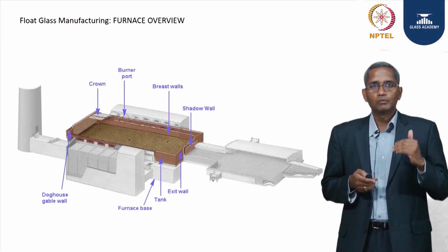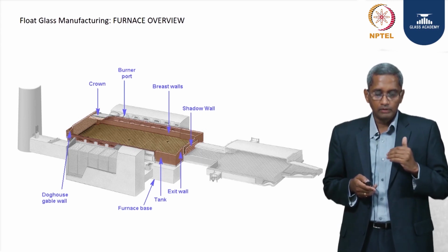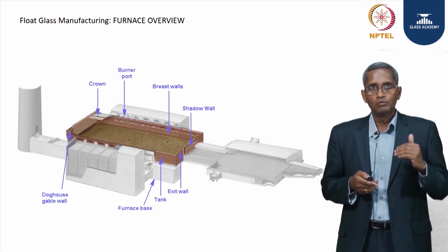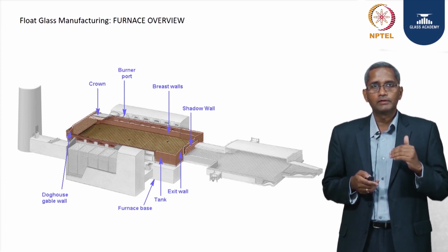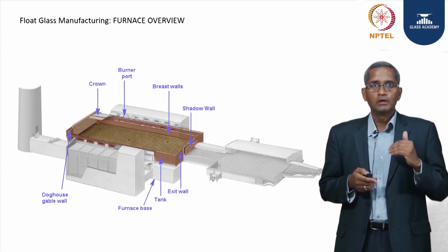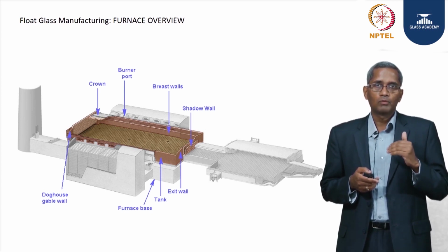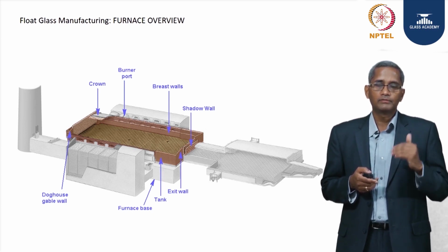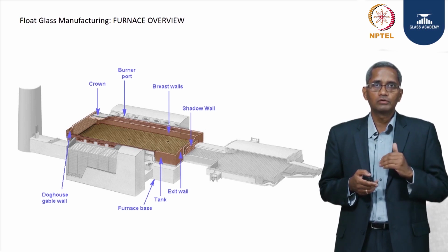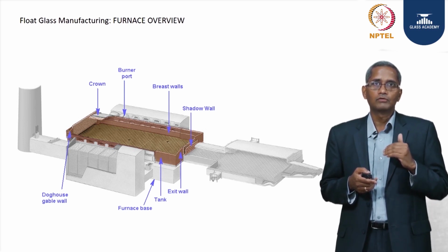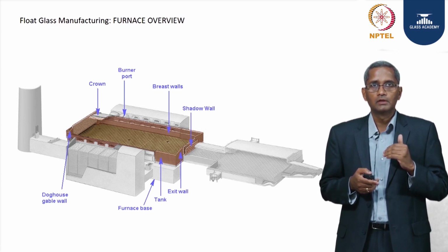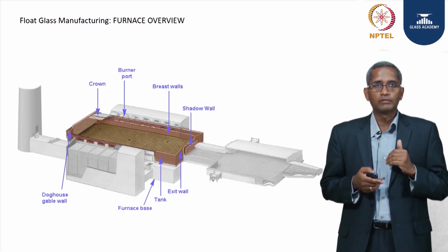So, the first is the melter, where the melting and refining happen, and then it goes into the neck. As you can see, the neck has a very narrow channel in which, having melted and refined the glass, we now need to bring the glass together thermally homogeneous, and also provide a few pieces of equipment in the neck, mixing equipment, so that we mix the glass together and the temperature of the glass is more or less homogeneous, which is also essential for the optical quality of glass.